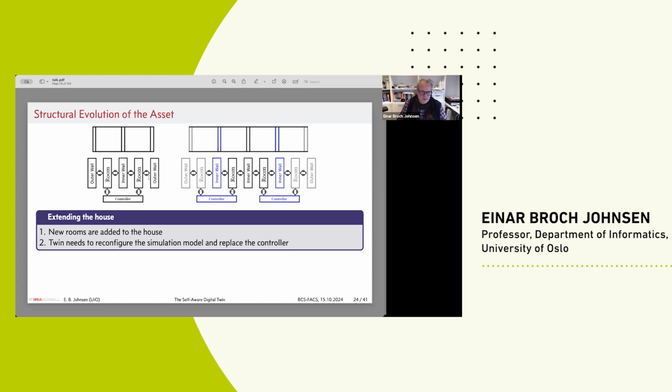So here we have the old office space, and now I'm going to add the lab here and the lab here. So we now have 4 offices. They will be connected. So the old outer wall here is now an inner wall. The old outer wall there has become an inner wall, and so on. And the controllers I have can only regulate the temperature in 2 rooms. So I had 1 controller for these rooms. Now I want 1 controller here and another controller there.